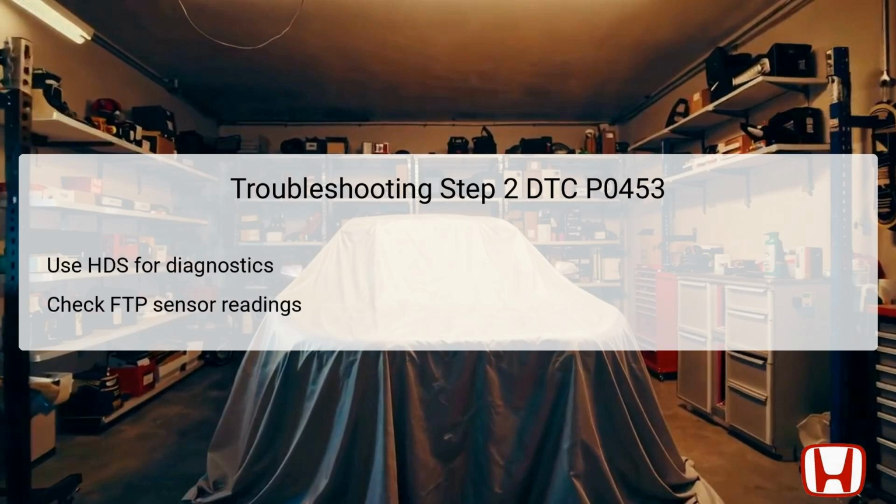The second step involves utilizing the Honda Diagnostic System, HDS, to perform a thorough diagnostic check on the FTP sensor. HDS is an essential tool used for reading and interpreting the vehicle's sensor data accurately. By connecting to the onboard diagnostics, technicians can observe real-time data from the FTP sensor and determine if the voltage readings fall within the expected ranges. Anomalies, such as consistently elevated voltage levels, can confirm whether the sensor is indeed malfunctioning or if there might be other issues affecting its function. This step is critical in pinpointing whether the issue arises from the sensor itself or from wiring-related problems, assisting in guiding further troubleshooting or necessary repairs.